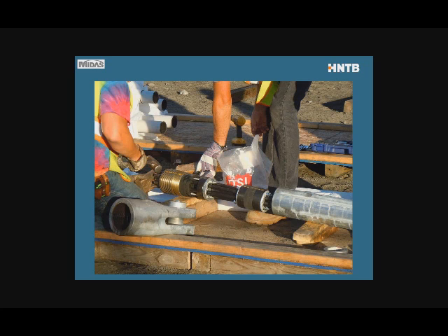Lake Champlain, by the way, was kind of a hybrid between the pinned connection with the traditional cable, or with the traditional wire rope, and the strand-by-strand that we use for Blennerhassett. Lake Champlain also has an I-shaped arch rib, similar to what I've shown for Happy Hollow. So we didn't really have room to seat wedges and to have anchor beams in the arch rib. So there, the idea is to prefabricate the whole cable in the yard, and you can see the cable being assembled. Lake Champlain only had 7 strands per cable.